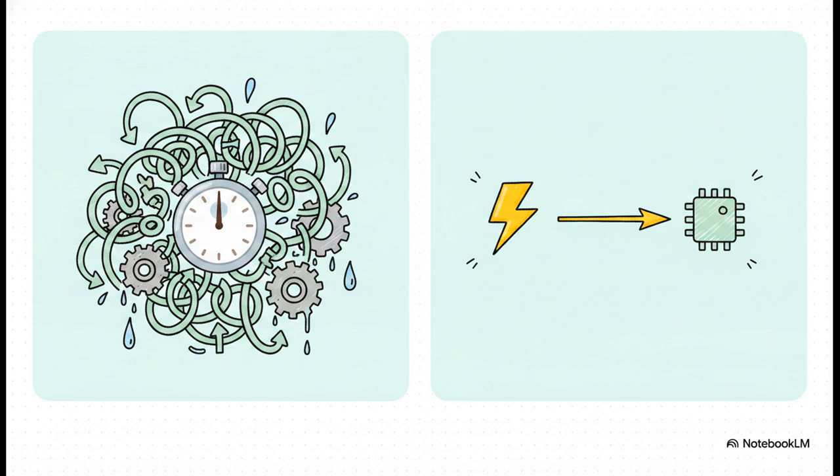Contrast that with a tag trigger. A tag trigger is highly efficient because it only queries the system when the actual underlying variable updates. It just sits quietly until the tag says, hey, I've changed, which keeps your overall system load remarkably light.